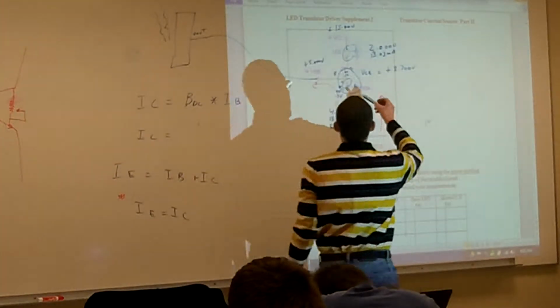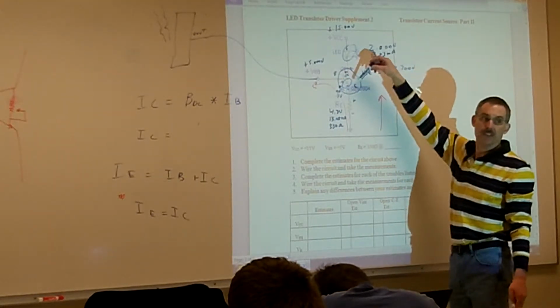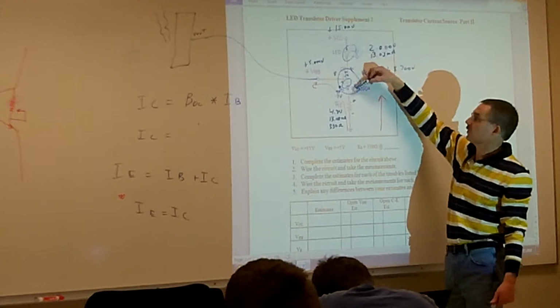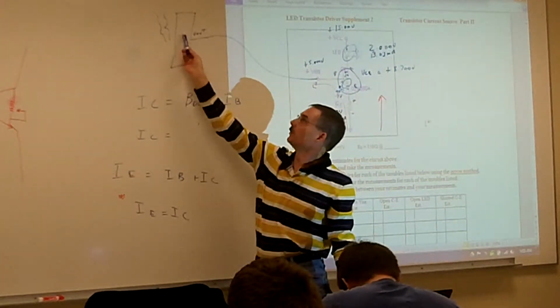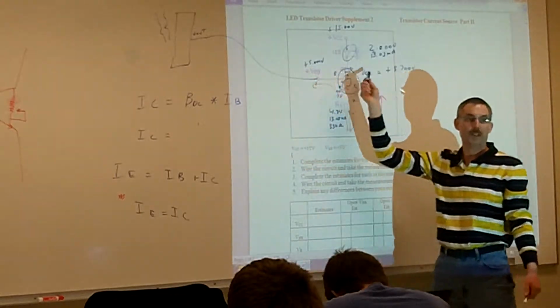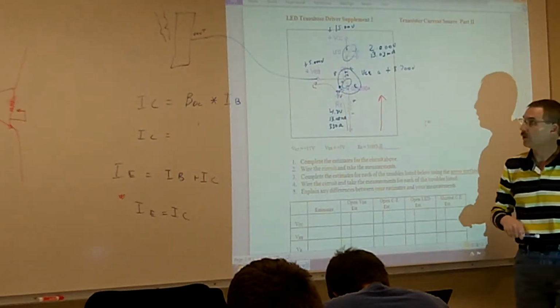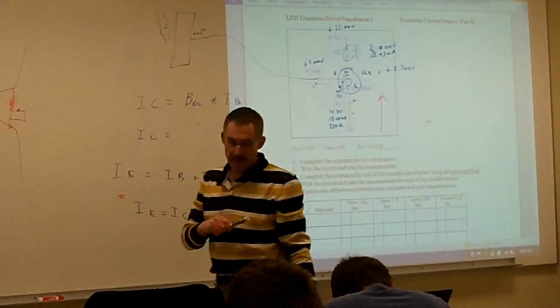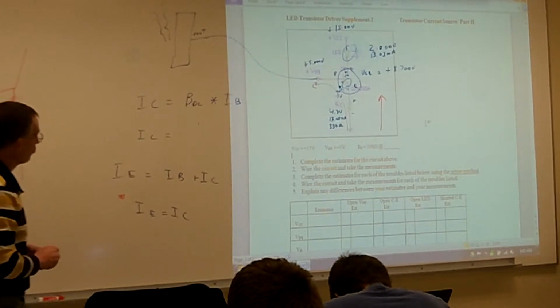Just because this one opened up, most likely this one isn't going to be burnt up because it just hasn't opened. We didn't get large amounts of current going through this thing. This one here got a lot of current, so that's why that one smoked. This one probably never did smoke because it never got the current. It's the current that's going to kill these devices, and that's what's going to smoke them. So be careful about replacing the component that's burnt up. That's typically not the culprit.